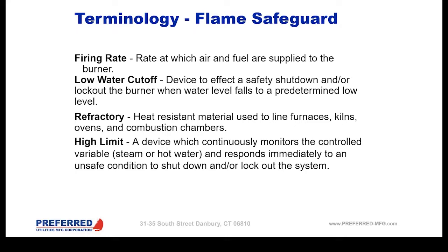Firing rate. This is the rate at which the air and fuel are supplied to the burner. So at low fire, we're going to be turned down as low as that burner is stable, to give us the largest amount of modulation range. So that firing rate could go from anywhere from, we say 10% a lot of times, to 100%. That's what we'll be referring to.